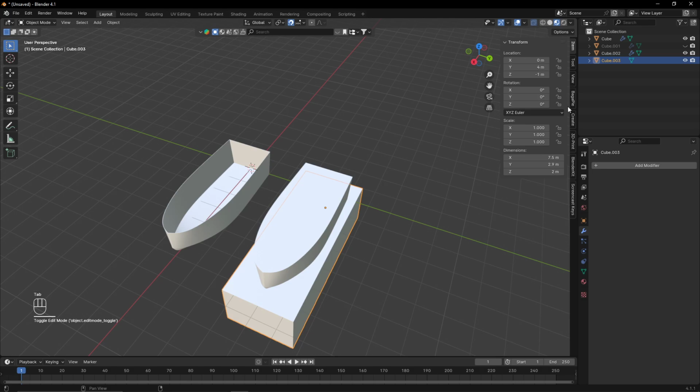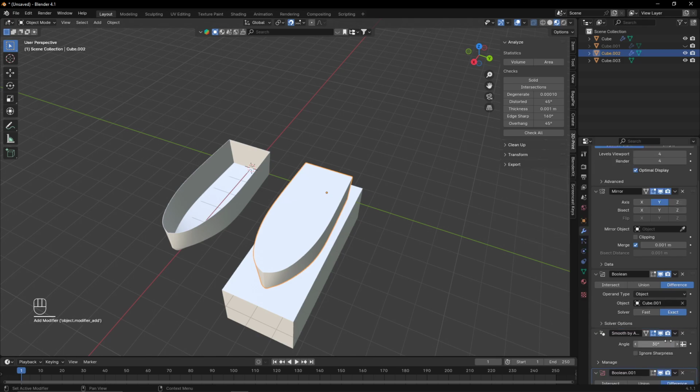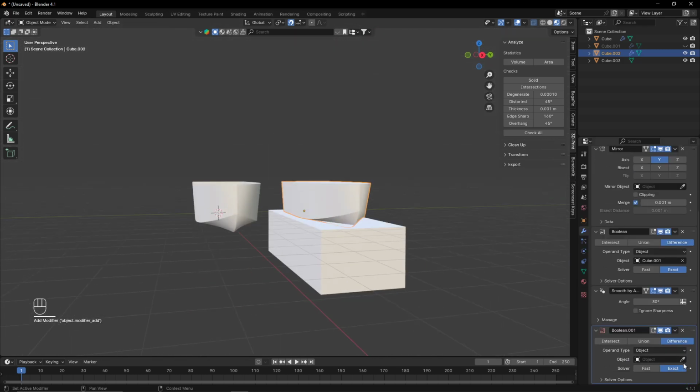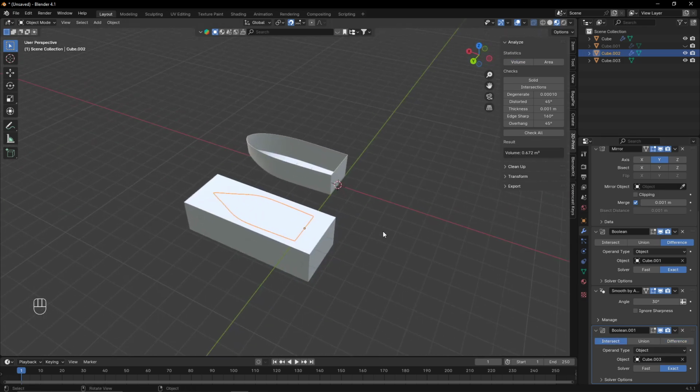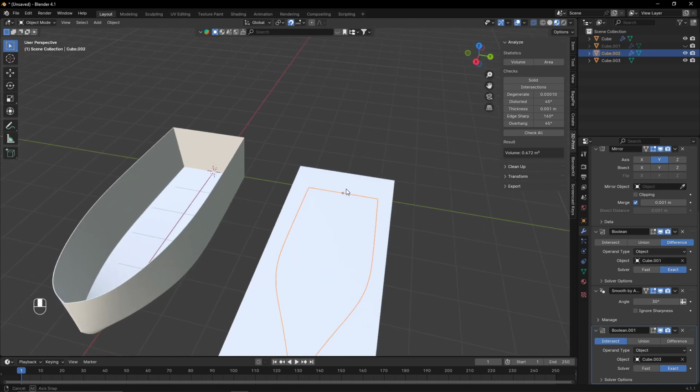Download the 3D print add-on that has a volume section, then Boolean from your hull to your waterline, intersect volume. This hull is for 700 kilos in salty water, 672 kilos in fresh water, in lake water.